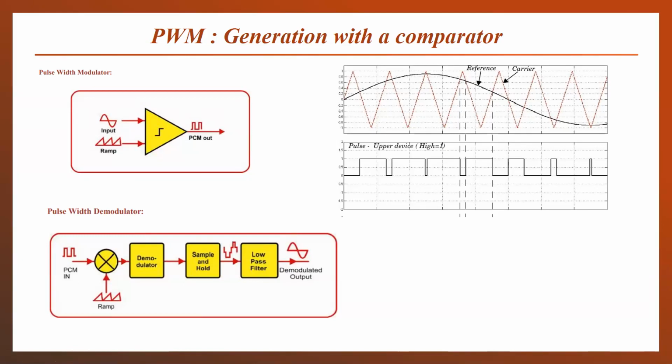and then the sample and hold circuit will hold the sample variations, and then these amplitude variations will be passed through a low pass filter, just like we have done in the pulse amplitude modulation, where an envelope detection was done followed by a low pass filter. So the same work will be done here. Firstly, we have to convert the pulse width or pulse time variations into pulse amplitude variations, and then the pulse amplitude variations will be detected through envelope detection and the low pass filter circuitry.